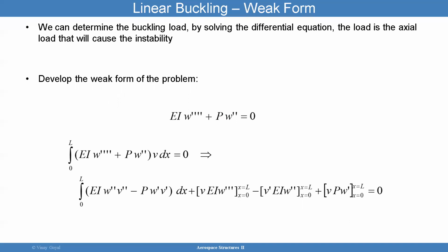When it comes to buckling, what you will often get is a linear buckling analysis, an eigenvalue analysis. It's an eigenvalue analysis that needs to be solved. But the procedure is very similar to what we discussed last week, in the last lecture, which I apologize for, where we take the differential equation multiplied by a function v, and we distribute these derivatives to v by integration by parts, which we're not going to show here because you can pull a calculus book to see how that's done. So just integrate by parts twice here, one time here, and then you get these boundary conditions that come up.